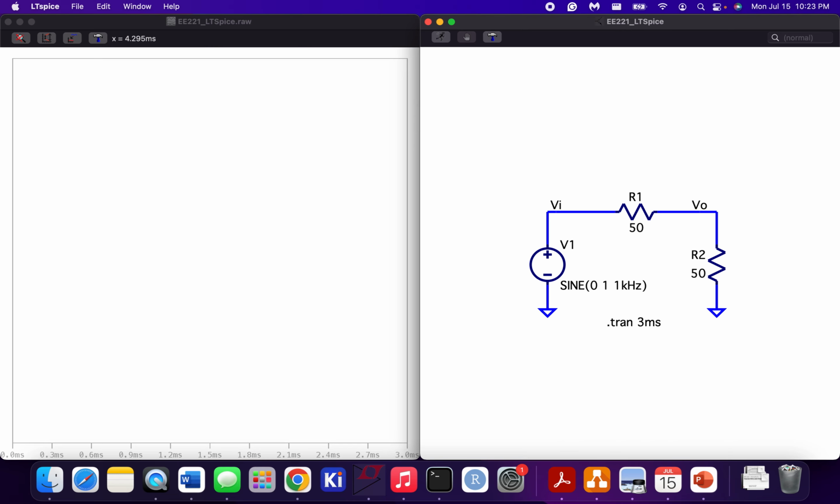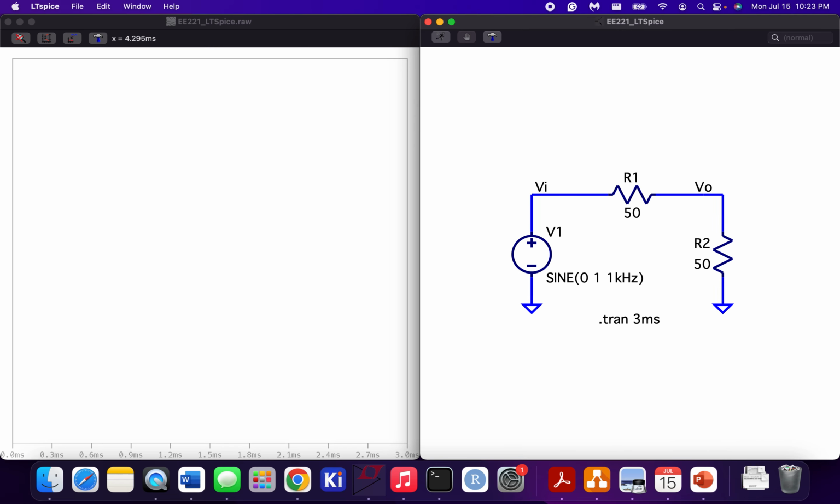And so what are we looking for? Well, we're looking for the power here. And so what do we need? We need the voltage. We were looking for the power across this resistor. Notice how the arrow for this resistor is pointing up, and this one's pointing to the left. That's what I was talking about. So I'm going to go ahead and rotate these because I want the current pointing to the right and then downward like this. So I'll rerun, and let's take a look at the output voltage.